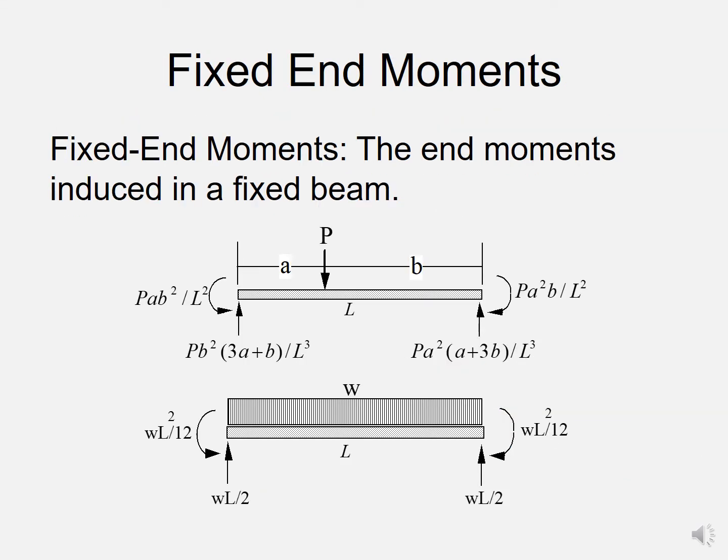Fixed end moments. One of the parameters used in the moment distribution method are the fixed end moments. So it's important that you remember the standard formulas for various types of loadings, such as concentrated load applied at the distance a and b from the left and the right, uniform distributed load, and other types of loadings.